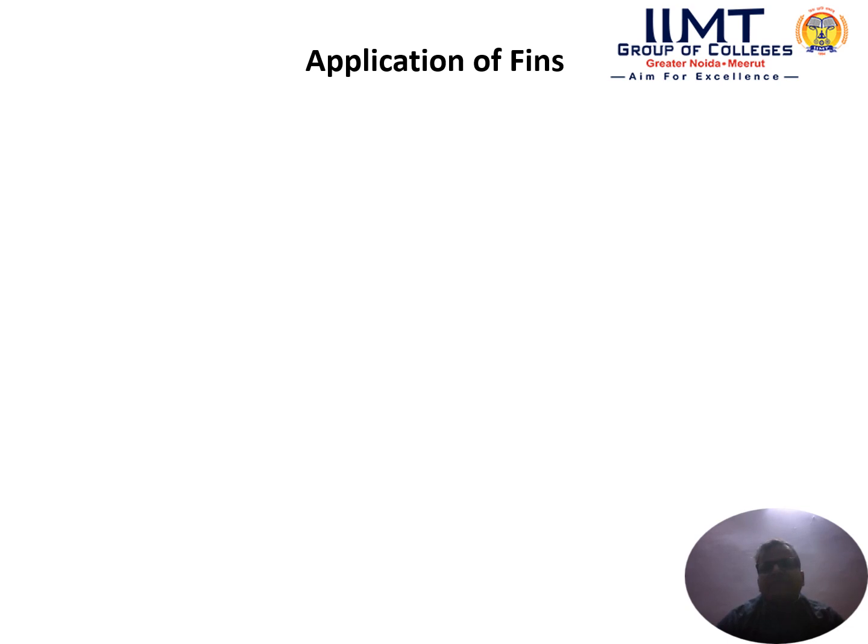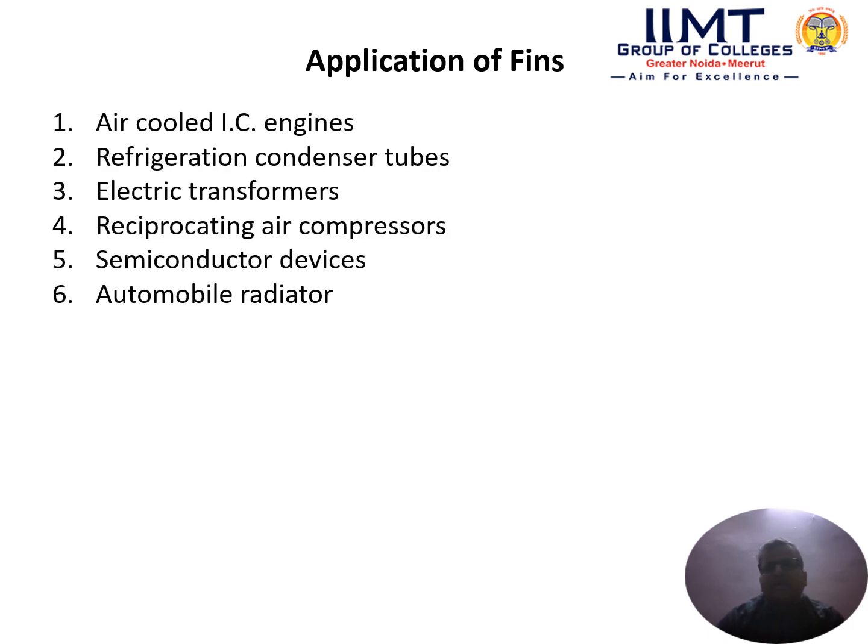Next is the application of fin. If we talk about the application of fin, there are n number of applications of fin. Number one, air cooled IC engine. If we talk about the air cooled IC engine, like a bike's engine, in that case we are using the fin for cooling purpose. Refrigerator condenser tubes in refrigeration, electric transformer, small scale reciprocating air compressor, semiconductor device, and automobile radiator. These are some applications of fins.